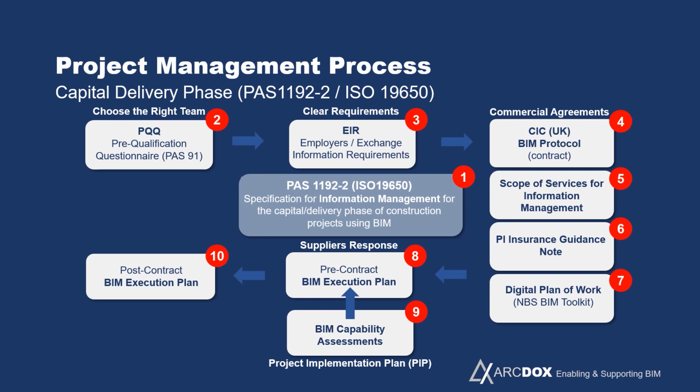Once people get appointed to the project, then they would contribute to what's called the post-contract BIM execution plan, and that's again a formal document which is then managed by the project information manager for that stage. So if it's for design stage, the lead designer, or if it's construction stage, the main contractor. And all the parties will be contributing to that document. So it's again the formal response of the supply side to the client's requirements.